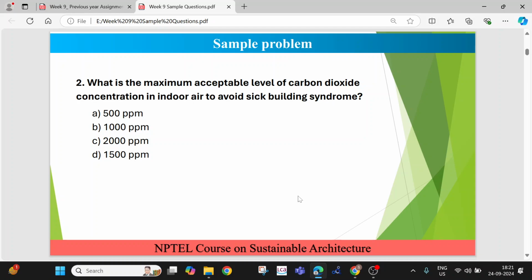It is not defined that if you maintain something like 1100 ppm and you are not feeling sick, then it is fine. If you are not feeling it instantaneously, it may still cause long-term effects. That's why 1000 ppm is the ballpark advised by most indoor air quality certification agencies. Below this is better, above this is hazardous. Is it fine?